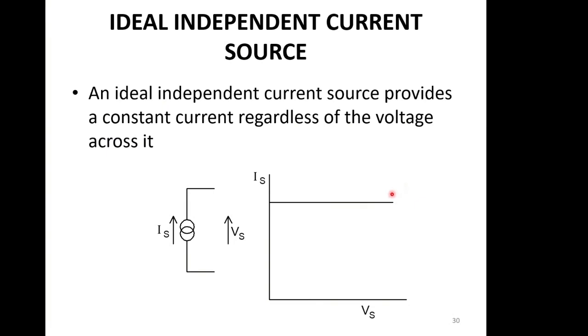And again, if you go to extremes, the extreme for the current source is when it's open circuit, as drawn here. Intuitively, you would say, well, there's no loop around here. There can't be any current flowing. And yet the current source is an ideal current source and therefore is forcing 1 amp to flow. It doesn't care what the rest of this circuit is. It's saying, I'm giving you 1 amp and I will do whatever is necessary to give you 1 amp, which is where this voltage can alter. This current source effectively alters its voltage to maintain this 1 amp. Now, in an extreme case, when it's an open circuit, it's really got to make this voltage huge so that the current can jump the gap.